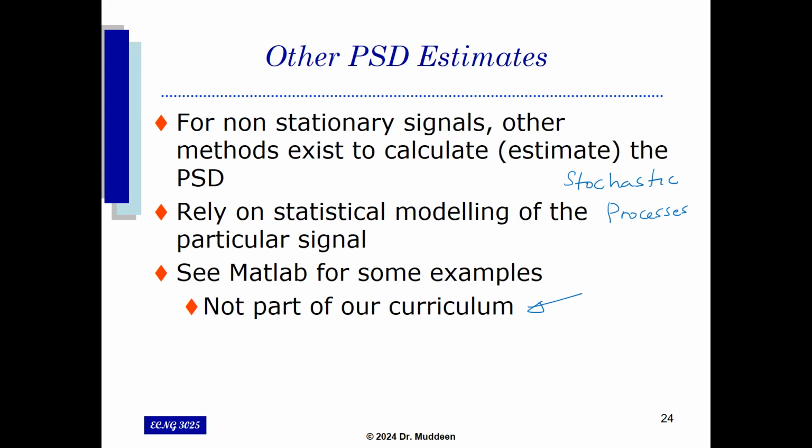On the other hand, if the signal has information in it, for instance, you're doing an analysis, and because of leakage there are components in the signal that are obstructing your ability to decipher what the signal is actually doing, then instead of looking at the raw amplitude of the signal, you can look at the power in the signal, and specifically something called the power spectral density.